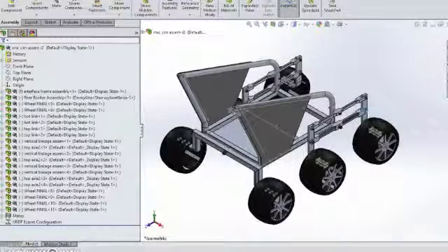For this example, we're looking at simulating the locomotion configuration of the robot. To do this, we have stripped down the extraneous parts from the assembly that we would not need, such as the upper assembly and the grousers that you saw on the wheels that provided traction. In this export, we're going to create the collision model. These grousers, that in actuality help increase traction, can't be used in simulation because Gazebo uses rigid bodies.